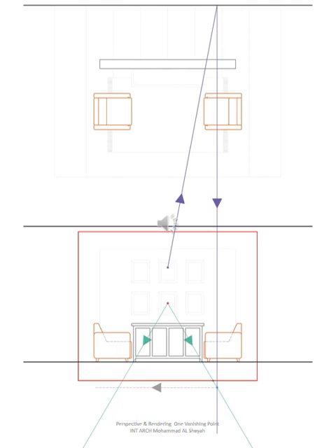Using the same method before, we will draw the plan of the desk by using the lines from the vanishing point to the projected points in the ground, and then using the station point to the corner of this object projected to the projection line and then going downward, thus forming the plane of the desk in the perspective.